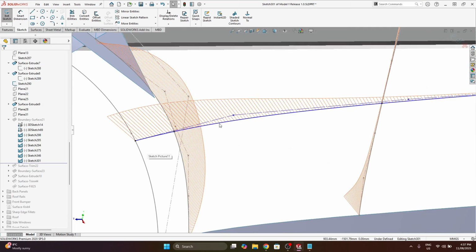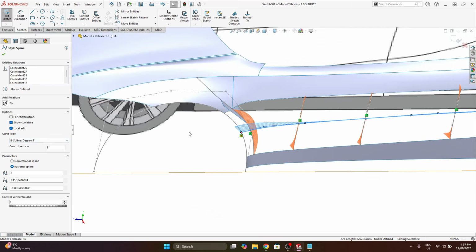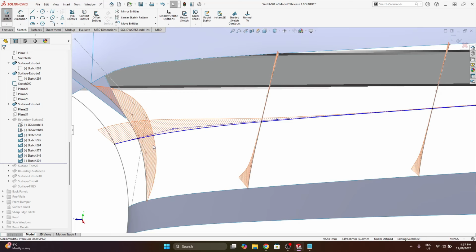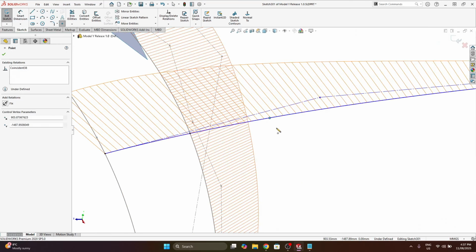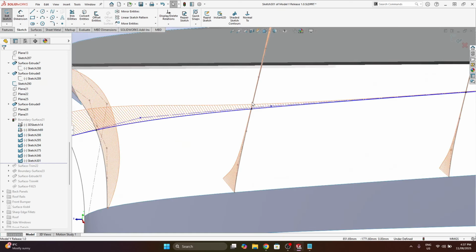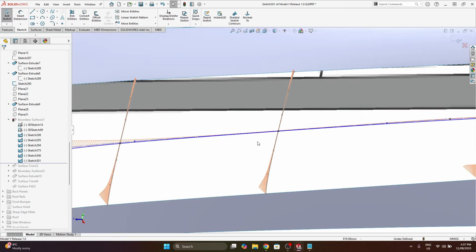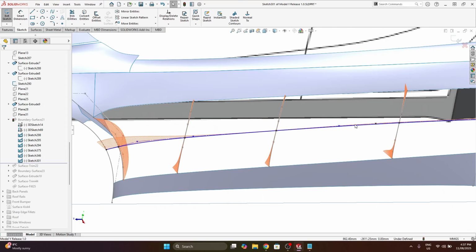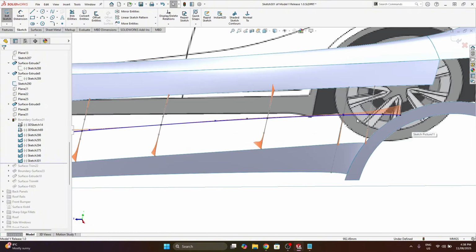And what I did is a style spline. This has many control vertices, 8. And then I've put in points. So I just come in and put a point on the 3D curve, and then make that point coincident with my guide sketches in the other direction, which you need to do, because if I'm using all of these guide curves to build a surface, all these guide curves need to intersect.